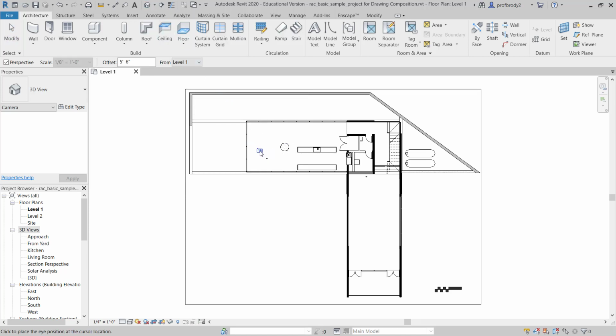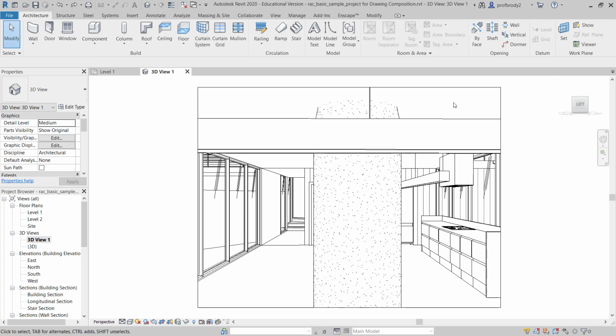when we think of where we put the camera, one thing you'll want to ponder is whether or not you want a 1-point or 2-point perspective. Now, how would you know that? Well, first of all, when you plant the camera, you'll see the triangular cone of vision. And if I look at, say, a corner, that's going to be a 2-point perspective. Whereas if I keep the line of sight, this center line of sight, perpendicular to some back wall, that's going to be a 1-point perspective. And again, it depends on what's in the space and how you want to show it. So here's my beautiful 1-point perspective that I set up with a column right in the middle of our face.